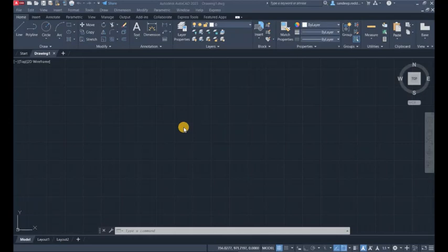So you draw a circle of a defined diameter in the XY plane, and you extrude. In AutoCAD you extrude along or parallel to the Z axis. So if you keep this phrase in mind, that you draw your 2D object in the XY plane, and to modify that 2D object into a 3D object, you extrude along the Z-axis or parallel to the Z-axis, you'll hardly run into any problems if you need to draw 3D in AutoCAD.